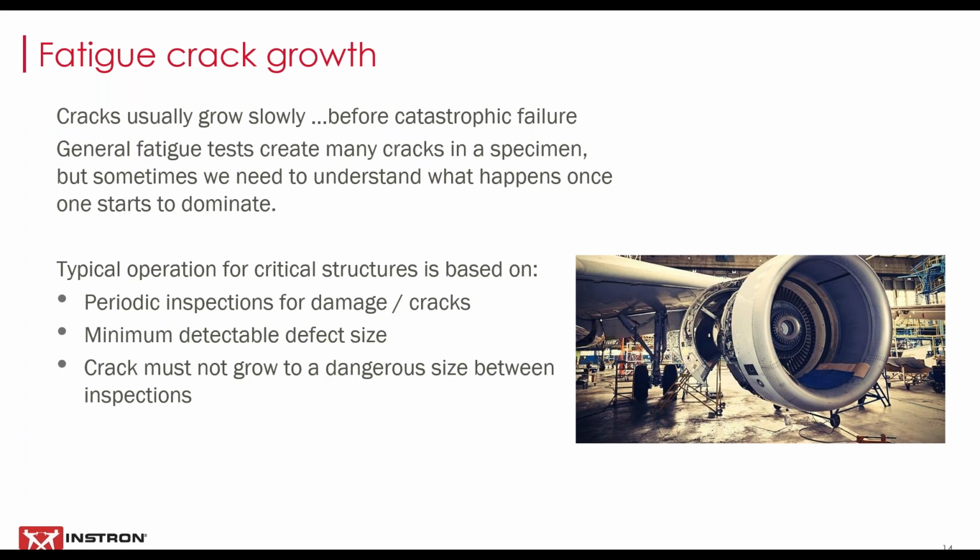I don't know what it is in their standards, but let's say it's something easy to observe with the naked eye. So you're going to do that every, let's say, 1,000 hours of flying. So what you need to work out is to be sure that your crack, if you get one, mustn't grow from not recorded to dangerous in that 1,000 hours between inspections. And to do that, you really need to understand how the crack grows under fatigue rather than under catastrophic loading.